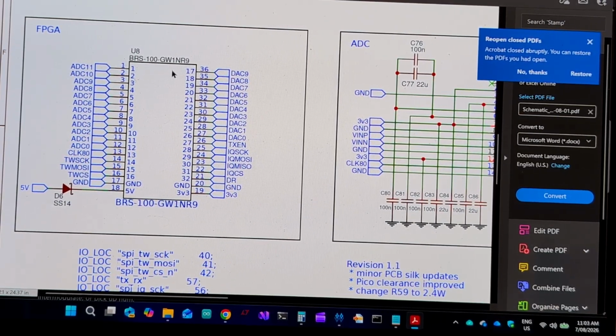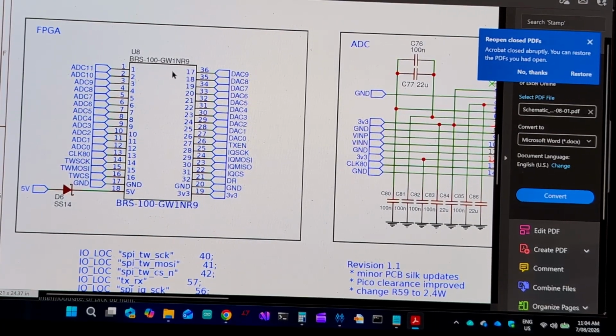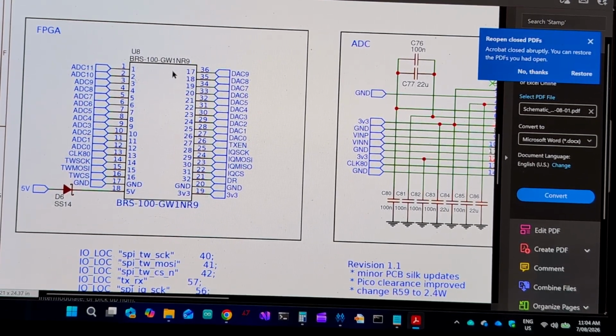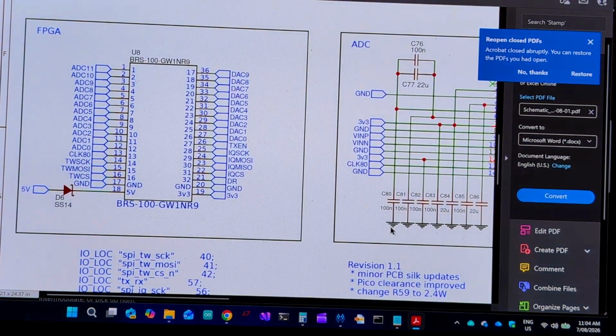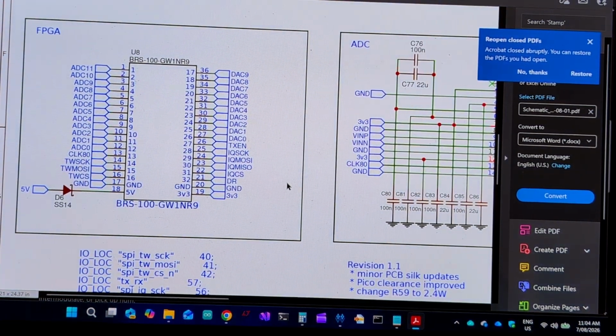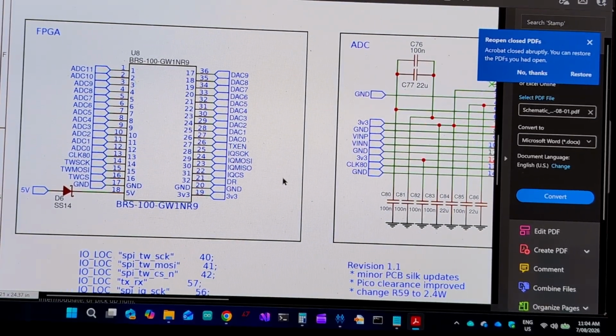It is possible to run, or it's an FPGA, so you can get it to generate an 81 megahertz clock, and then we change the divisor so that instead of decimating by 2560, you decimate by something else. I forget what it is. But in the meantime, I'm using TCXO at 24 megahertz.